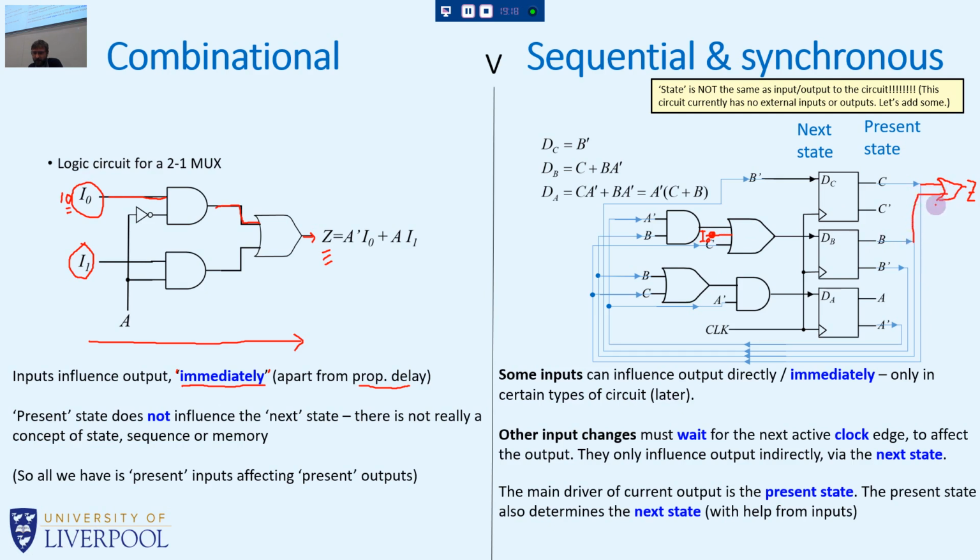What else should we do? Why would I lose a mark on this slide at the moment in an exam? Can anyone tell me? You input the dots. Yeah, so there's no way of knowing if this is a junction or this is a junction, etc. So put a node at least, or put a bridge there at the other place if you need to, if you